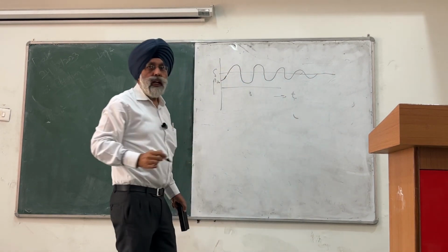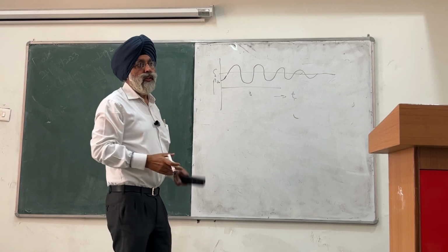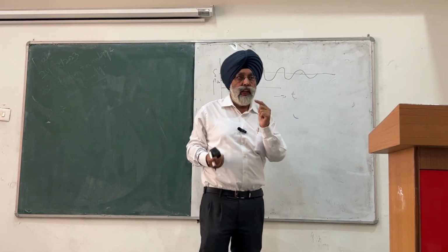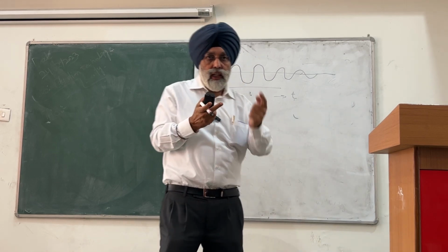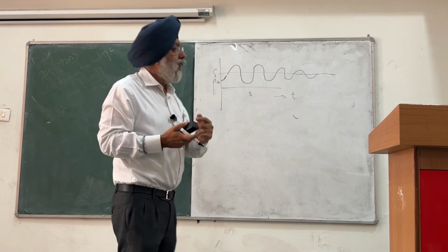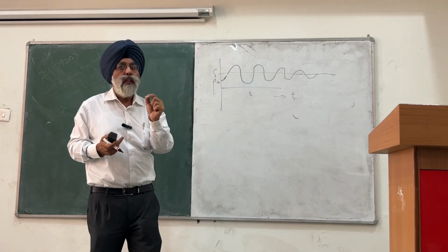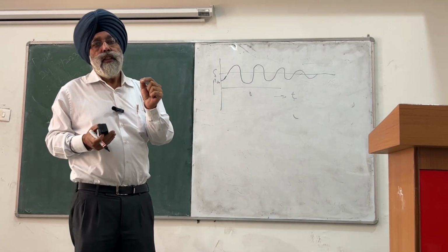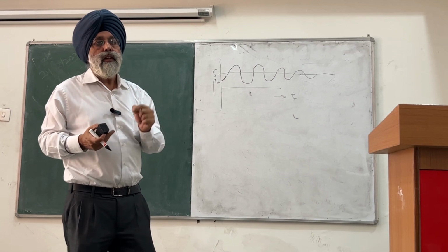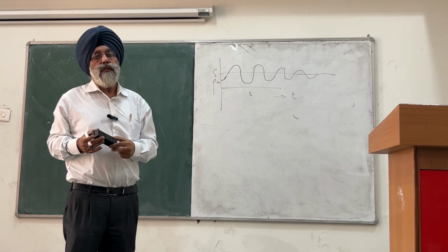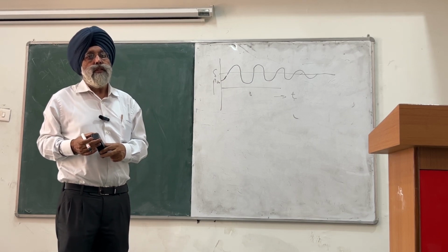new delta value. So we can say that after the disturbance, if your delta settles down, meaning delta starts reducing or the rate of change of delta after any disturbance becomes 0, we can say our system is a stable system. Otherwise, if your delta is continuously increasing, then we can say our system is an unstable system.